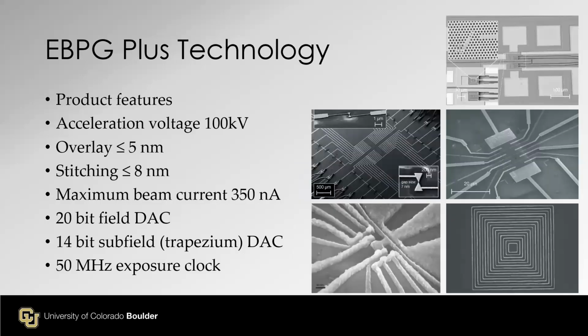So recap: 100 kV, overlay better than 5 nanometers, stitching better than 8 nanometers, maximum beam current 350 nanoamps.